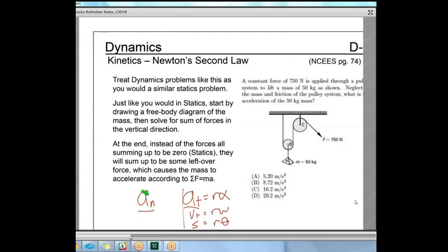A sub n is that normal acceleration. That's what gives rise to the tension in a string as you swing a rock around, a rock tied to the end of the string. It's also what gives rise to the force of the car pushing on your shoulder or your derriere as it's trying to get you to follow a curved path. So it's the n is for normal to your path, and the t is tangential to your path.